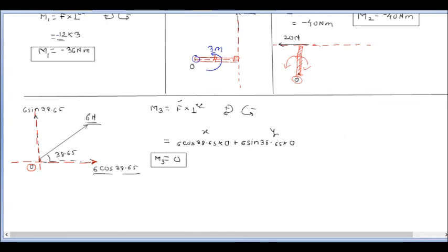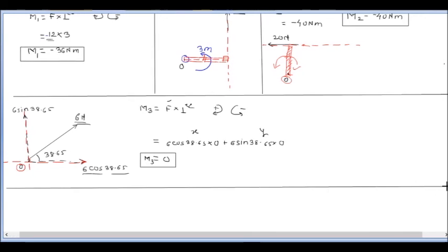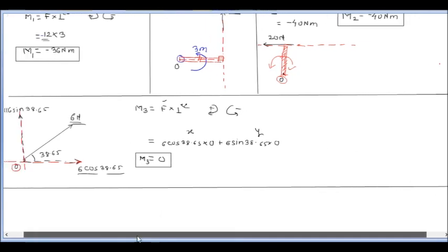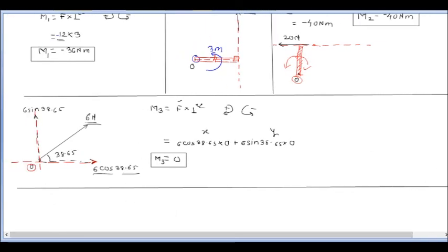So this way we have calculated the moment because of all these forces. Now what are we going to use? The final equation, by using Varignon's theorem or the principle of moments: the sum of all moments about any point, I have considered that point as O, is equal to the resultant and its perpendicular distance, which we are going to find out.